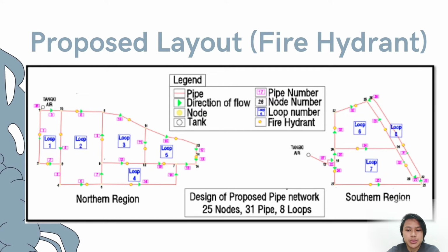And this second plan shows the location of the fire hydrants along the lines. By referring to the Malaysian Water Association Design Guideline for Water Supply System, this proposal is for light industry, thus considered Class C risk, which means a maximum of 1 fire hydrant is needed for every line of water piping flow.